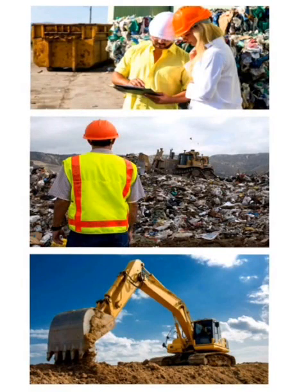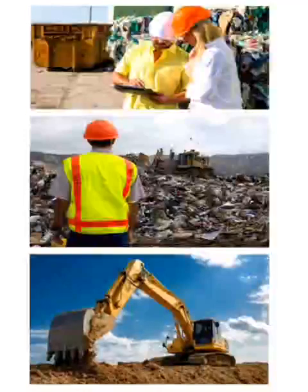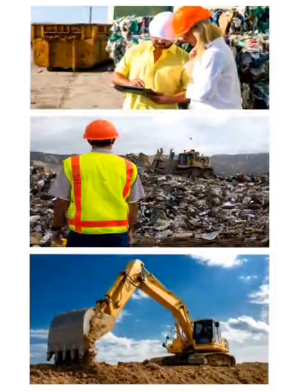Part of the waste is introduced into the excavated hole and is buried for decomposition. And of course, the waste that is applicable for such disposal is biodegradable waste, like paper, wood, timbers, soap, food materials, and so many others, the ones that microorganisms can work on to decompose inside the soil.